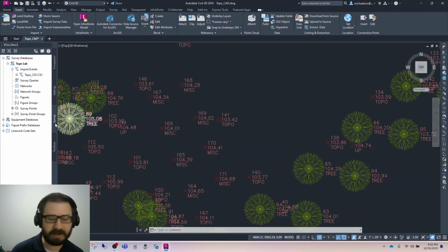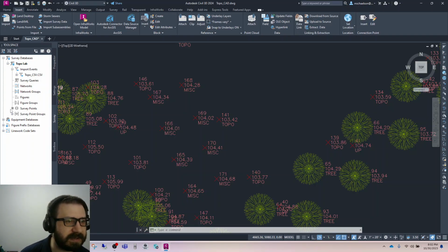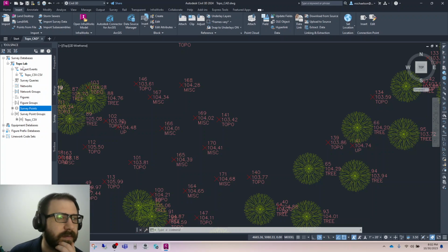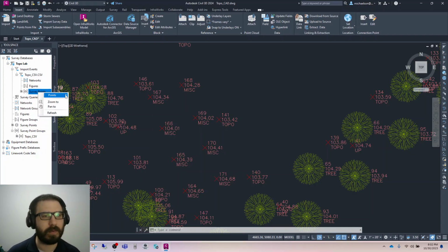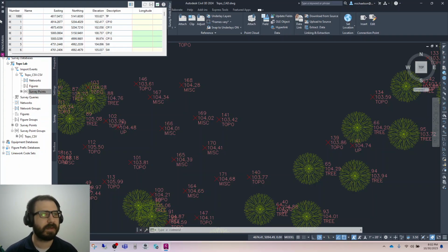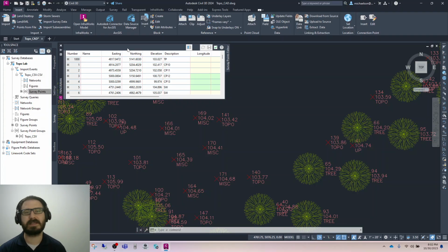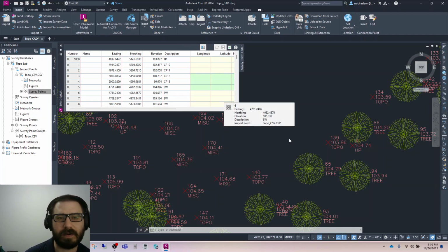What we're going to do is go into survey, and then survey points. Let me close this down here. Oh, sorry, I went to the wrong one. I went right here. That's where I want to go: the topo.csv. So right-click here on points, and we're going to go to edit points. What I did is I went into the import events, I went to my comma separated value, and I went to edit survey points. That's going to bring up this little spreadsheet that looks like this, and you can go in and actually start editing your codes and whatnot.